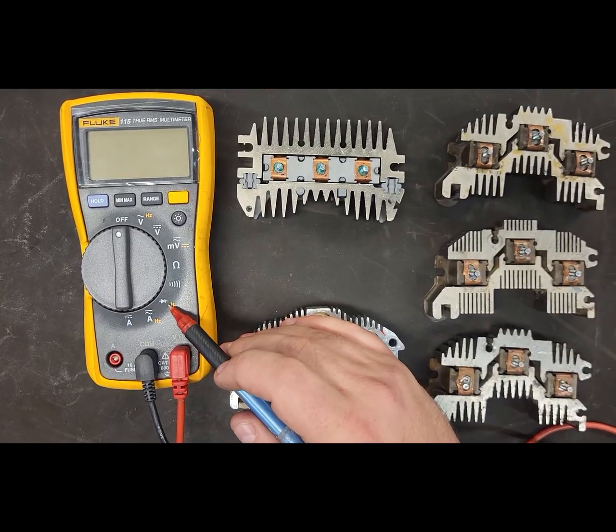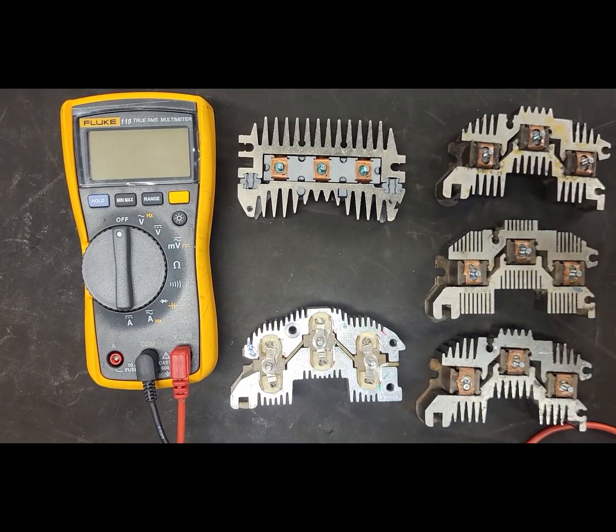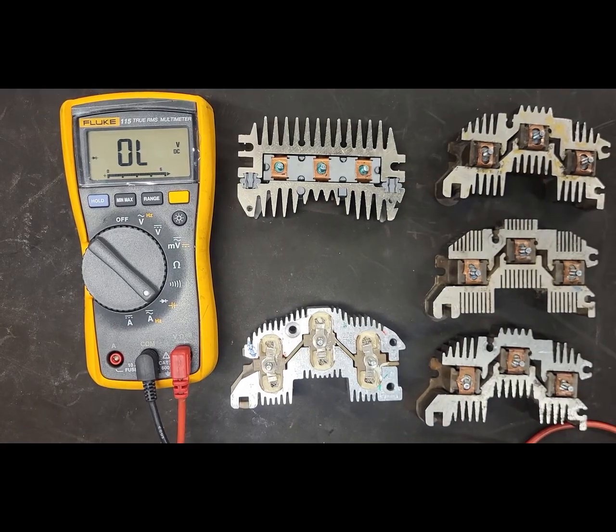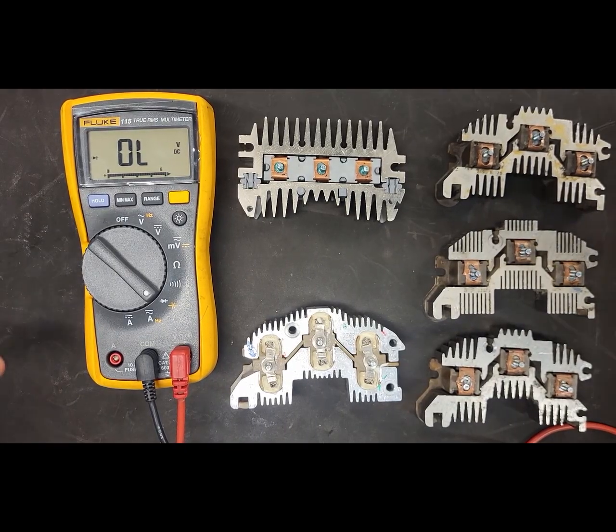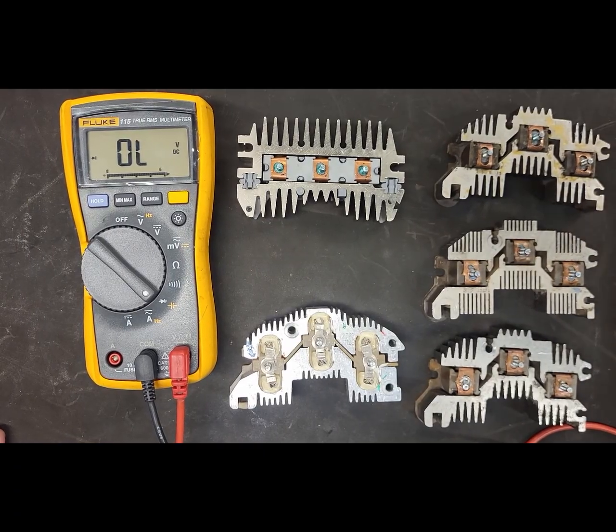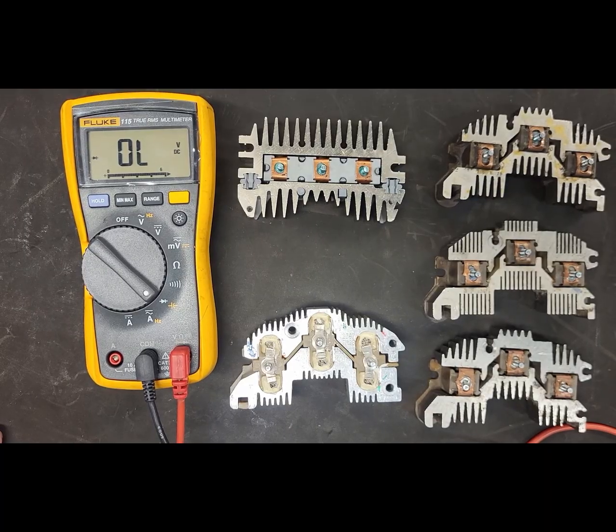What the diode function test is going to do is it's going to induce or input a specific voltage, and that voltage value that we read when we do a diode check will be the activation voltage. Sometimes I call it the opening voltage, but I don't like using that term. I'm trying to get it out of my vocabulary because it sounds like we're opening that diode in a failed condition. That's not what I mean by that. That's the activation voltage. Now that should be somewhere in and around the 0.5 volt range.